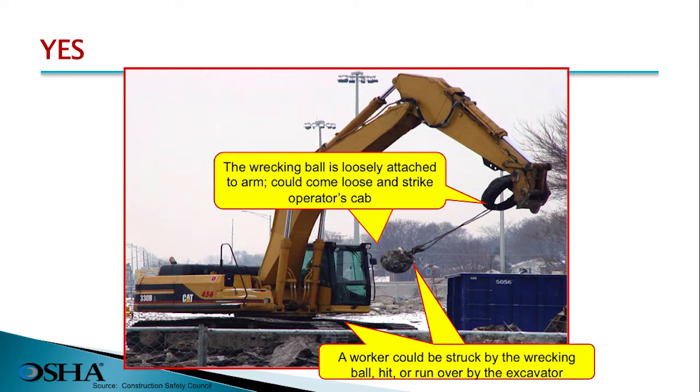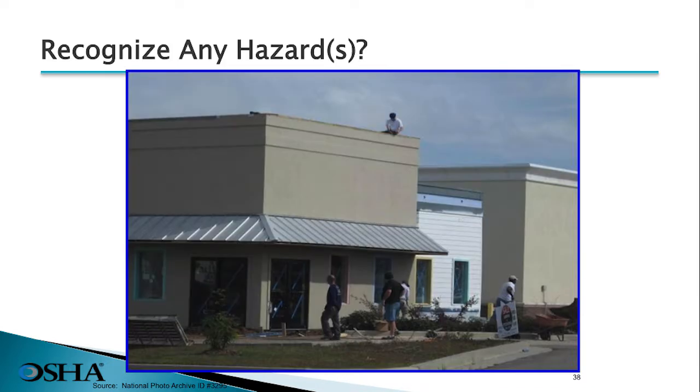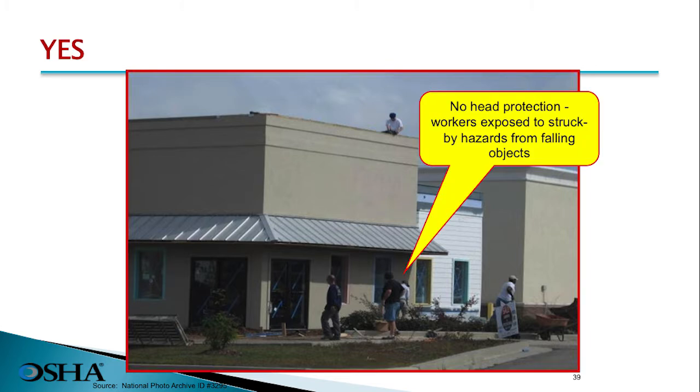In addition, a worker could be struck by the wrecking ball or hit or run over by the excavator itself. Do you recognize any hazards on this job site? The workers below have no head protection and are exposed to struck-by hazards from falling objects.